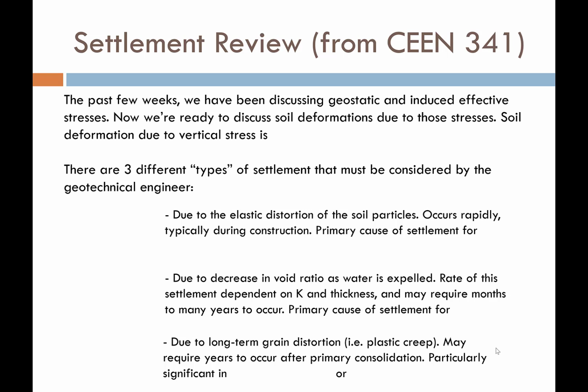When we talk about settlement, basically the idea is that the soil behaves somewhat like a spring, and the spring has a load on it. If we change that load, either take load away or add new load to it, that spring is going to deform. It's either going to elongate if we take load away, or it's going to compress if we add more load.